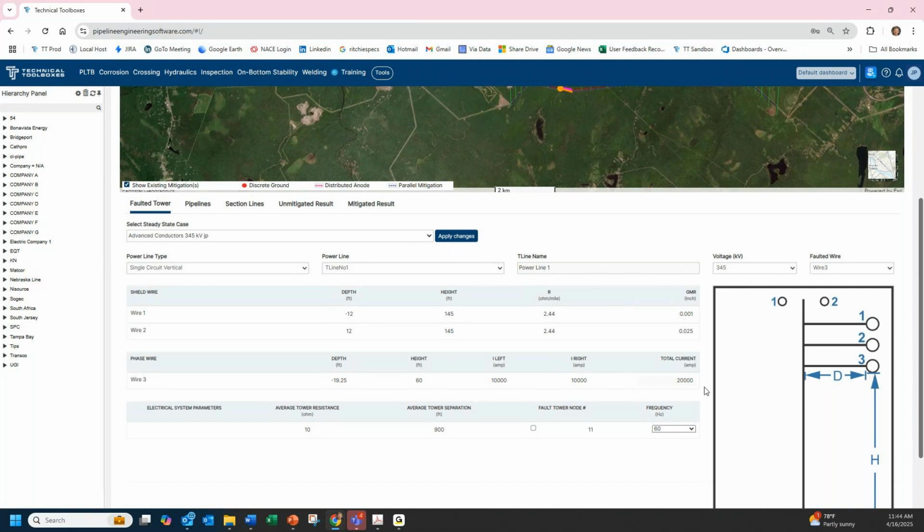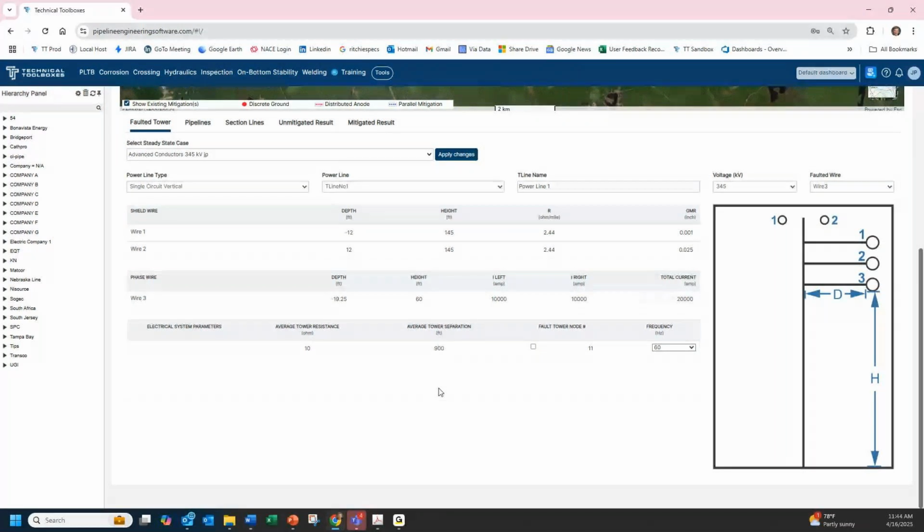You take the lowest conductor, and then I took out this shield wire. But what's happening is it's going to be a split. If the tower is hit, it's going to go to the left and the right, but most of the current, induced current or conductive current, is going to go down the tower legs to the ground rods.